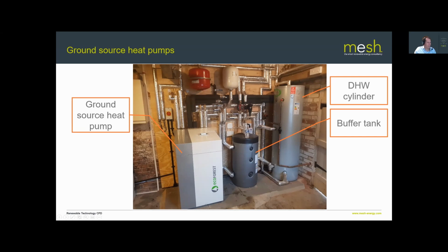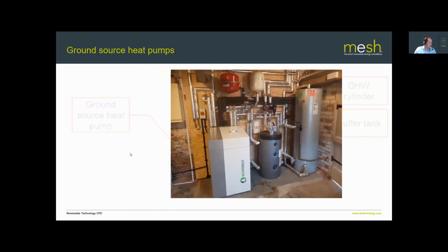The other thing to consider is just the height of domestic hot water cylinders. They can be quite tall. So if you've got particularly restricted ceiling heights, then that's something to consider. And obviously the takeoff for the domestic hot water tends to be on the top, so you have to allow a little bit of space above the height of the cylinder for that takeoff.